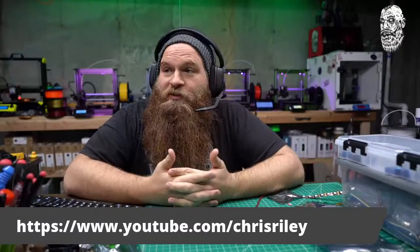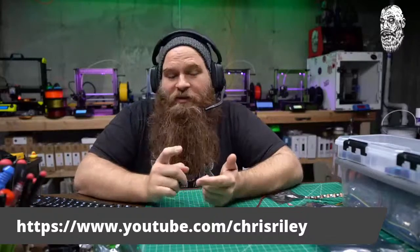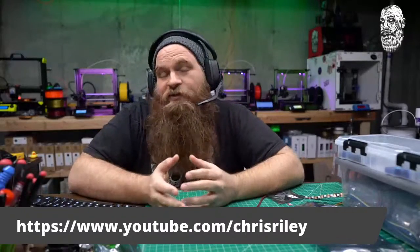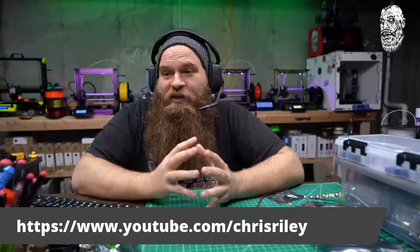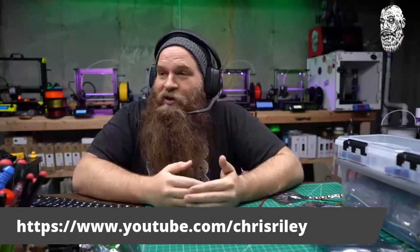The board limits what you can and can't do, because certain Marlin features take up a lot of memory. A Melzi board, like on a CR10 and an Ender, has a very limited amount of space, so certain features we're going to talk about won't fit. This is one of those things that really gets people in a loop. They'll say, I want to add all these features, how come it won't work?